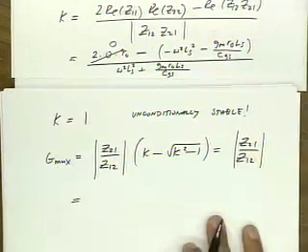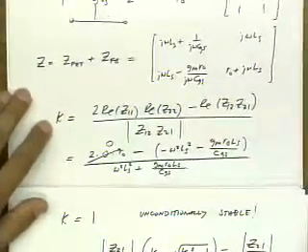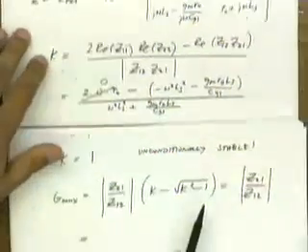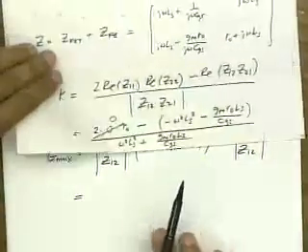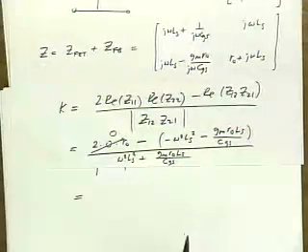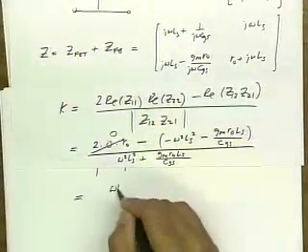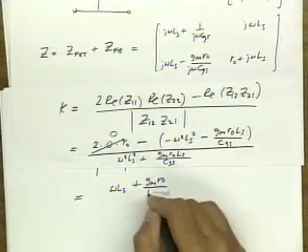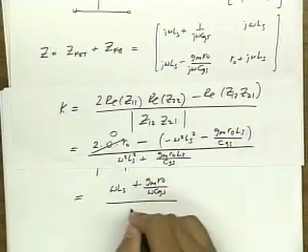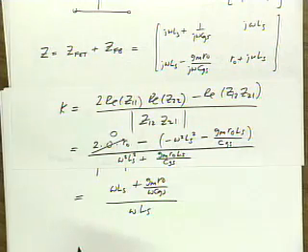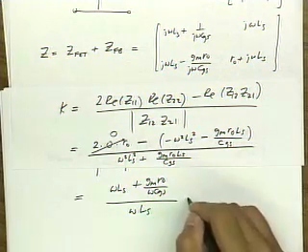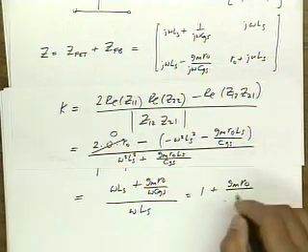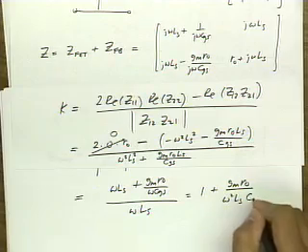And Z21 we found, this is Z21 magnitude, and this is Z12. So if I just substitute here, sorry I can't show both. I can try. Yeah. So Z21 magnitude is omega Ls plus gm Ro over omega Cgs, over omega Ls. And if I simplify this, this turns out to be 1 plus gm Ro divided by omega squared Ls Cgs.